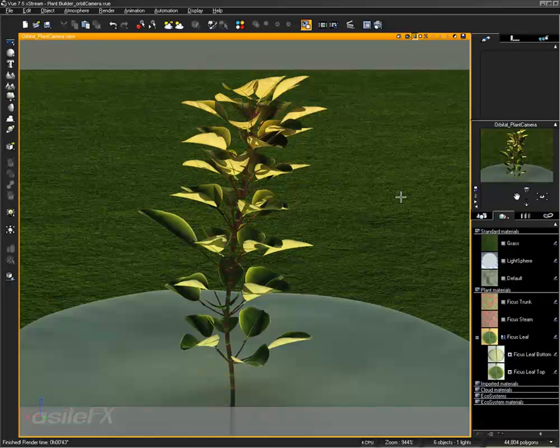And now it's probably too difficult for you to tell with the size of this render, but there's a common issue with every plant in view, or just about every single one, and it has to do with the bump map. Basically, one half of the plant will show it correctly, and the other half will show it inverted. Even when using the double-sided leaf materials, whether it's the default view one, which is using a mixed material, or the one I'm going to show you.